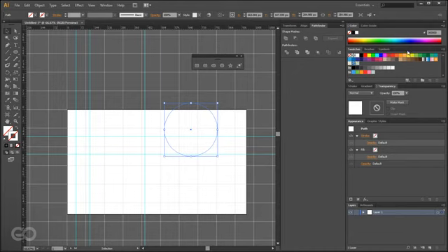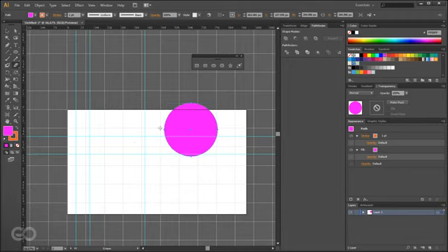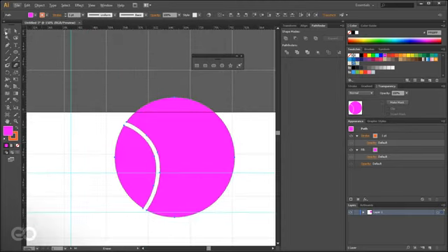Let me apply a color on this object. Now when I just applied the color on the object, the stroke was active, so that's why I used X on the keyboard to switch it to fill and give a different value. I can use the eraser and just erase through an object. As you can see, it's quite easy to get this kind of detail done.